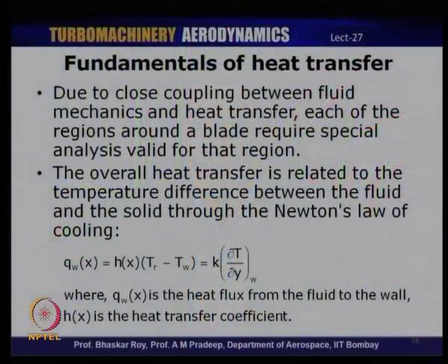Now, I mentioned that there is a very close coupling between the fluid mechanics and heat transfer, especially in the context of turbine blades and turbine cooling essentially. So, analysis of the flow around a blade requires special analysis which is valid for that particular region. For example, if you are looking at a laminar flow, that is the leading edge of a turbine blade, then one can analyze the heat transfer through a laminar boundary layer. And as we transition and go to the later part of the turbine blade, the boundary layer is turbulent and heat transfer through that boundary layer is quite different.